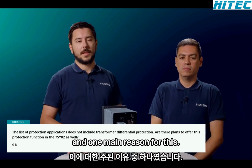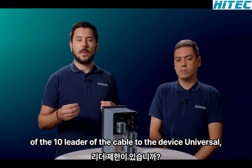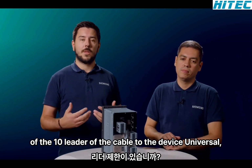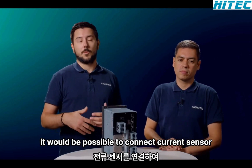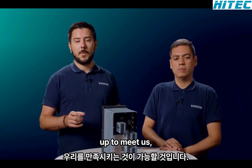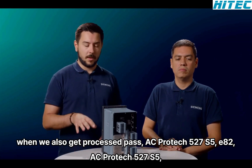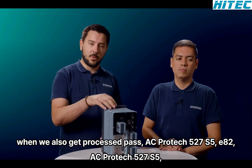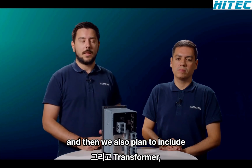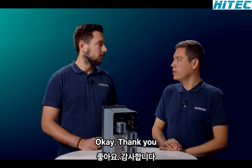And one main reason for this, which I also kind of explained earlier, is this limitation of the 10 meter cable to the device. The inputs, as it was mentioned, there are 8 universal LPIT inputs, so it would also be possible to connect 8 current sensors. But because of the length of 10 meters, we decided to include this one later when we also get process bus on our non-modular SIPROTEC 5 devices, including the 7SY82, which is planned for spring next year. And then we also plan to include transformer differential protection. Okay, thank you, Lars.